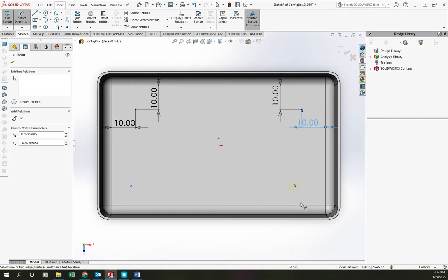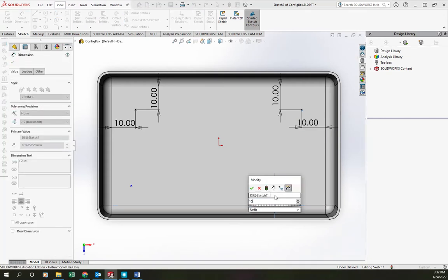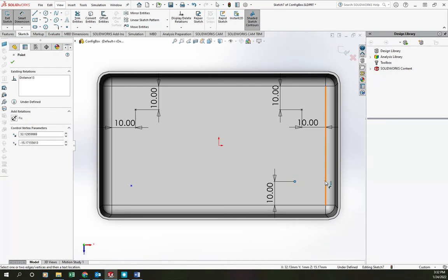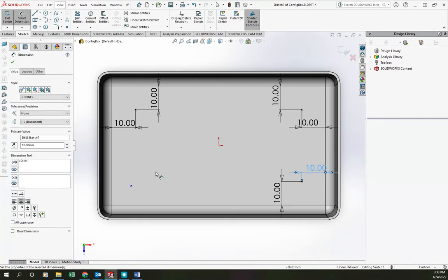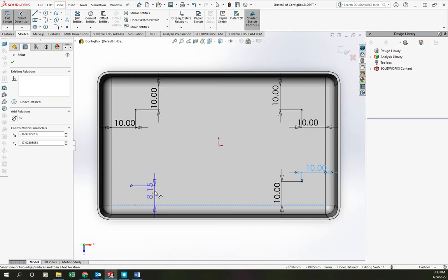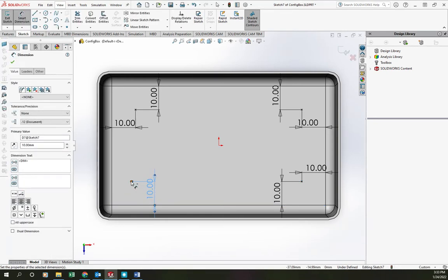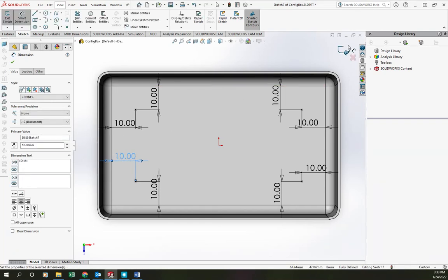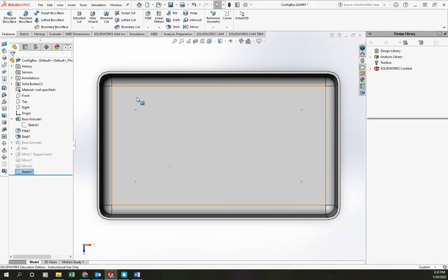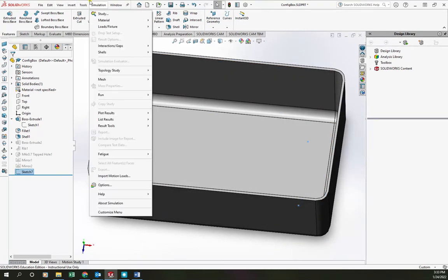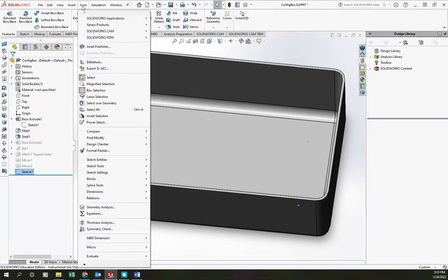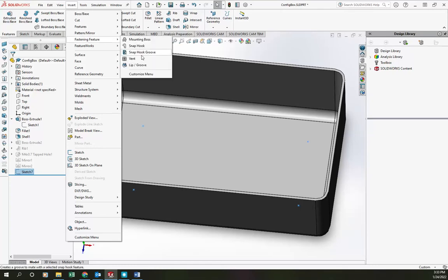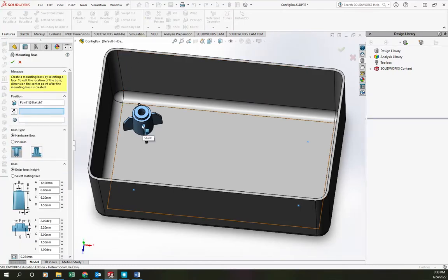If you want to use different values, moving them horizontally in and out from the sides is probably a little bit better than vertically. Or you can use a slightly smaller mounting boss to better fit into the box if it gets too small. But all of these 10s should work fine for this example. Alright, we've got our positions there. Now we can move to our mounting boss. So I'm going to rotate that a little bit. Going to my tools, insert fastening feature, mounting boss. I've had that last point selected already. If you don't have the location selected, you can always just click on the point.